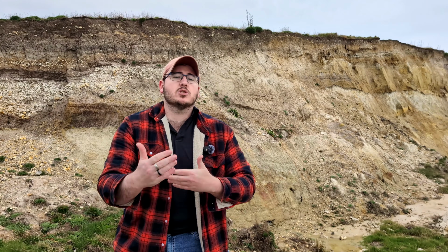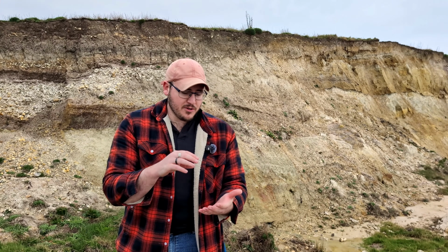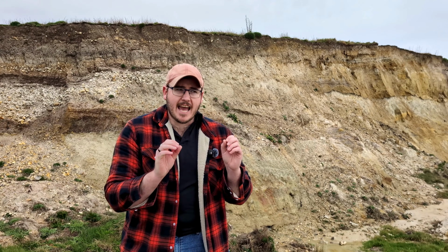And even at work, I use Pilot 2 all the time to mission plan, and it's a great convenience. But do you need that to capture photogrammetry data? No, you don't. What you need to be focused and mindful of is the overlap between the photos you're capturing and what sort of data you're capturing to begin with, because that's all it really requires. And if you're looking at the logger itself and at your Google map with your flight paths on it, you can guesstimate what sort of overlap you're going to be getting, what sort of data you are going to be capturing. And that's nine times out of ten sufficient when you gauge it accurately enough.